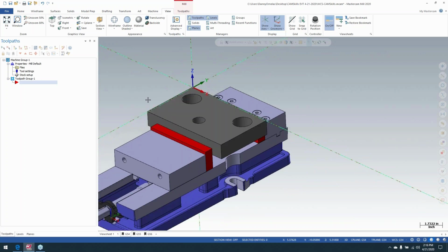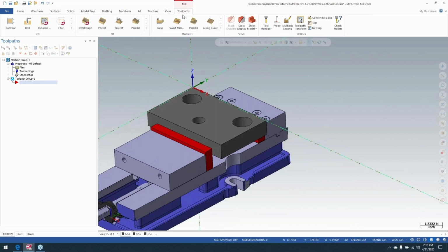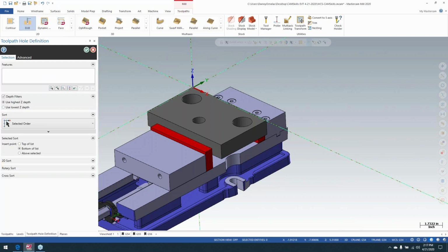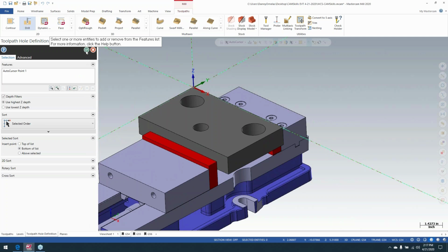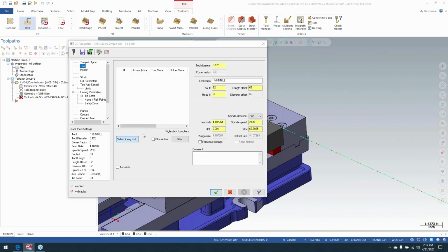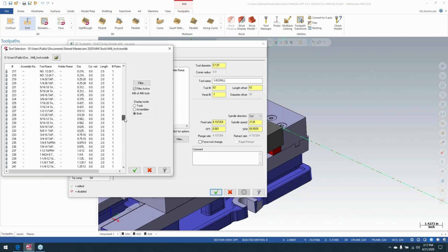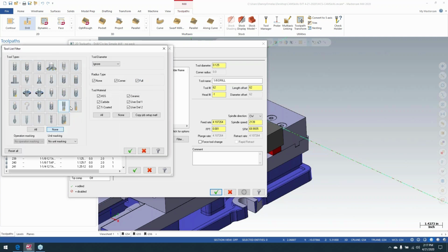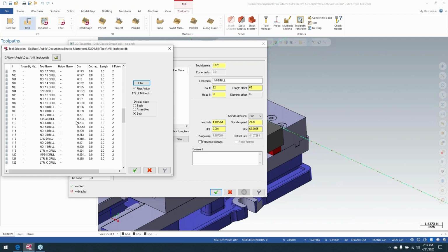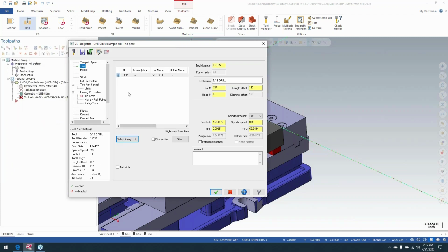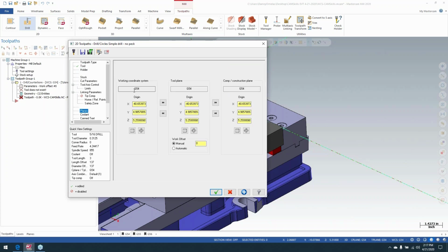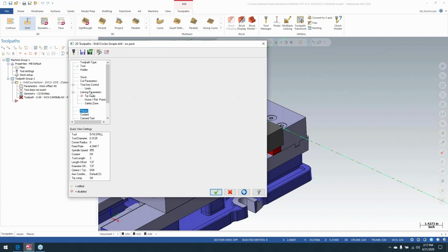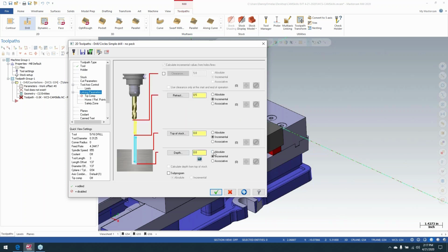So I'm going to take this first one here. So I'll give you several toolpath examples. Go to toolpaths. I'm just going to do a drilling operation. I'm going to drill that point right there, right in the corner. Get myself a good sized drill here. Oops, I got nothing but temps. Grab a 5/16 drill. And on the planes, they're all set to G54 right there, right? Link in parameters. I'm just going to take this to a depth of -1/2 inch. We'll select OK to that.